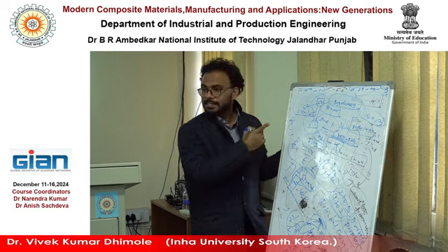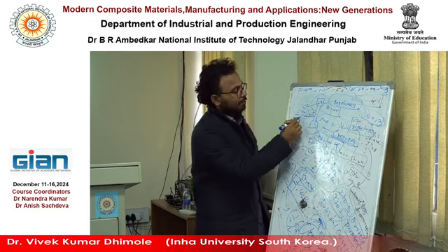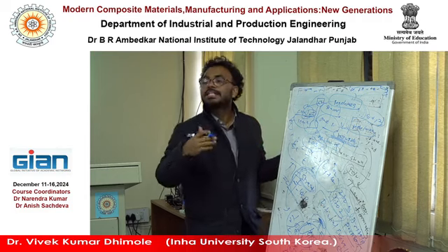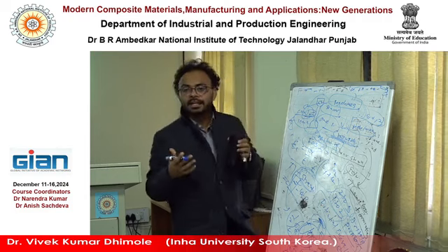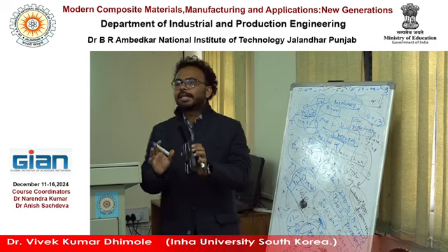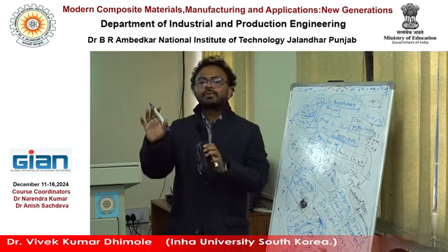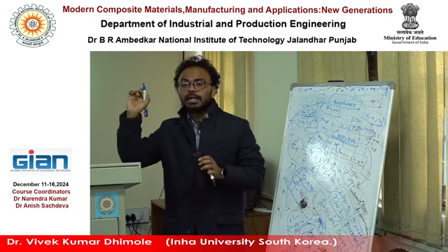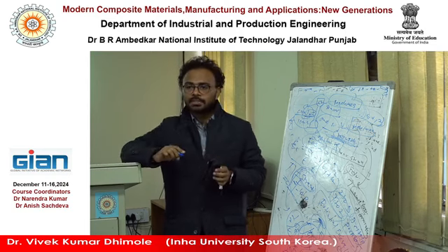But you say no, stress is coming very high, we cannot go 10 mm, we have to reach 15 mm according to this analysis. So we can increase the thickness or increase the length, something like that, right? So finally we can propose the design, this proper design is now valid for manufacturing, because we are studying the composite one, and composite manufacturing is very expensive, right?